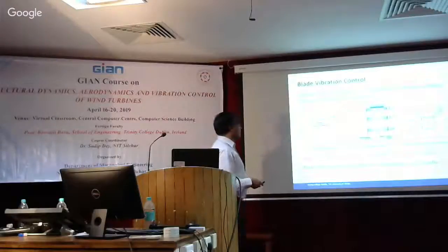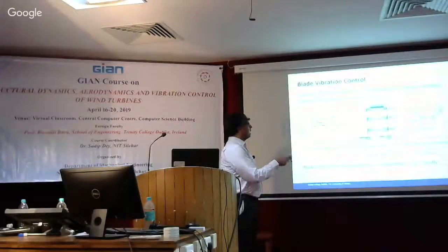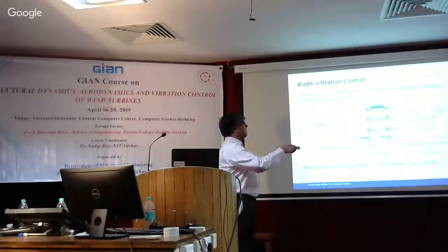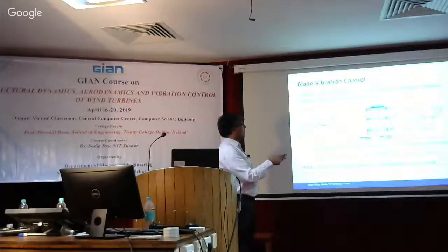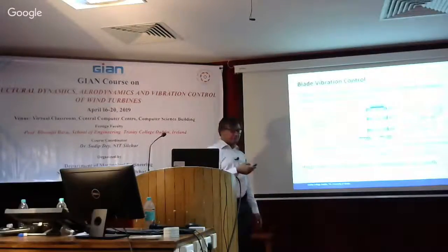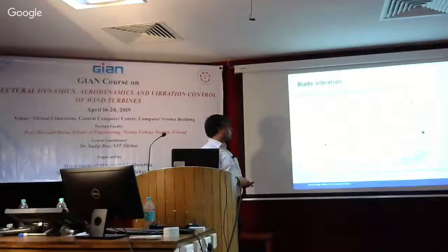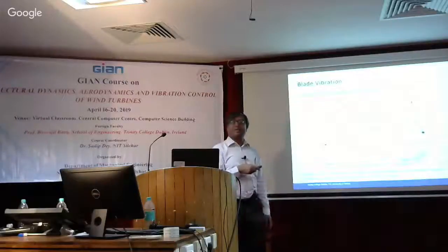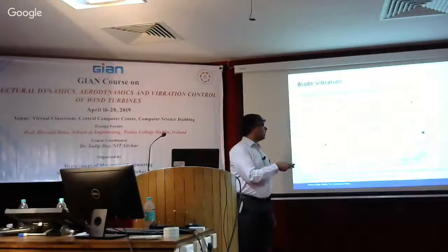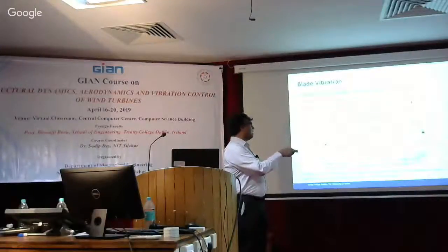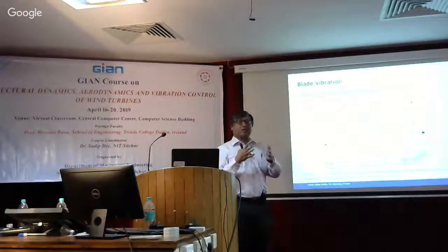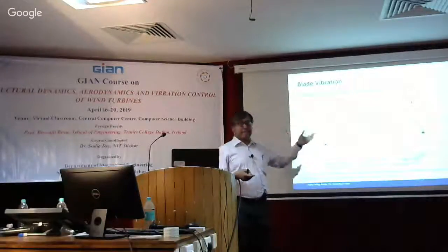Now, in all these cases, like the tuned liquid column damper, the tuned liquid damper is also another means to suppress vibration, or maybe a mass device in a kind of circular pathway can also do the same. It's a roller damper. We looked at both of these, including some full-scale experimental studies of these dampers as well. The roller damper, this is a paper in Sound and Vibration, can also have the same effect. Essentially, this is the liquid column damper, but with a mass instead. The advantage of the liquid column damper is that you have less wear and tear, because if you have a solid body moving in a slot, then there's a lot of impact and friction. But with a liquid, that's not there. So liquid will not have the wear and tear that a solid body will have. That's another advantage.